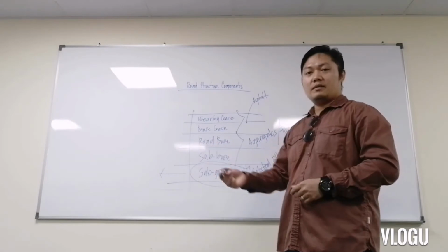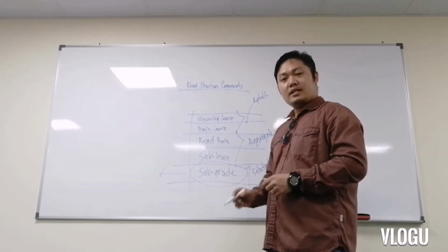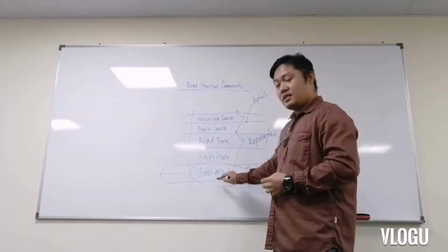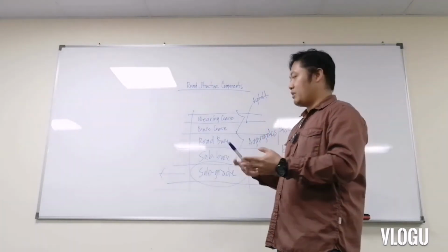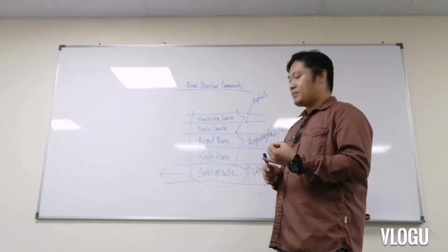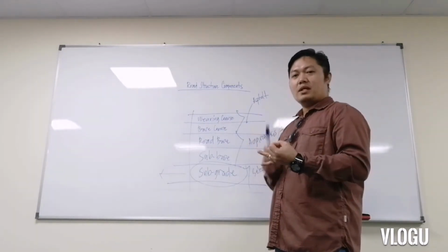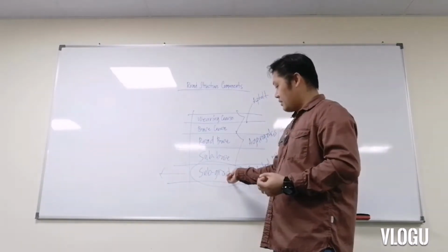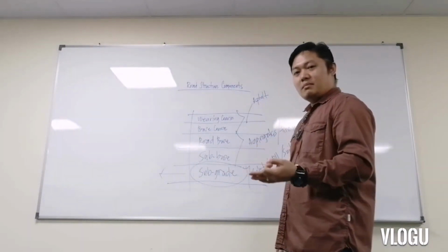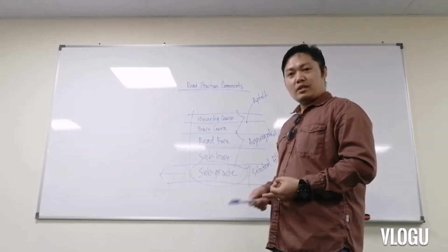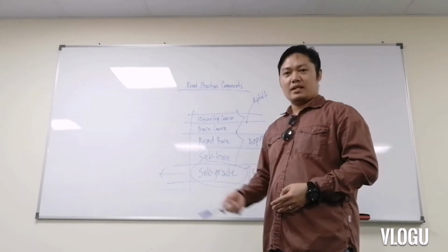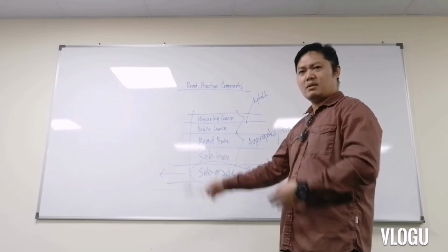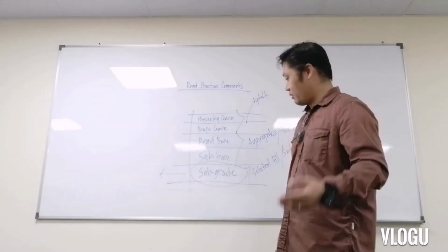Sometimes we have to take samples in this particular area. We have to determine the different types of testing in order to ensure that this is suitable to be used. Let's say, for example, when we take a sample, we have to identify the gradations, and at the same time the Atterberg limits. We are going to determine the plasticity index of the subgrade, and also the OMC, or optimum moisture content, and the MDD, known as the maximum dry density. We also have to determine the pH content, and do chemical analysis also if it is required.